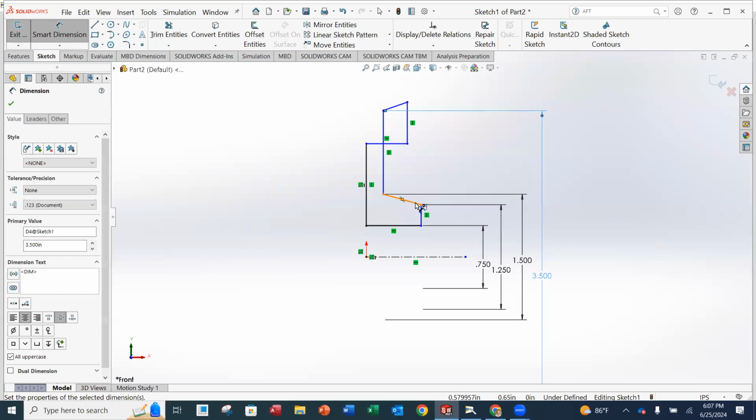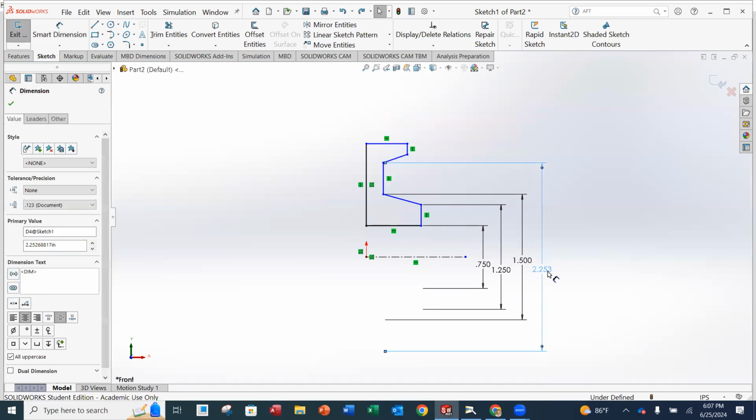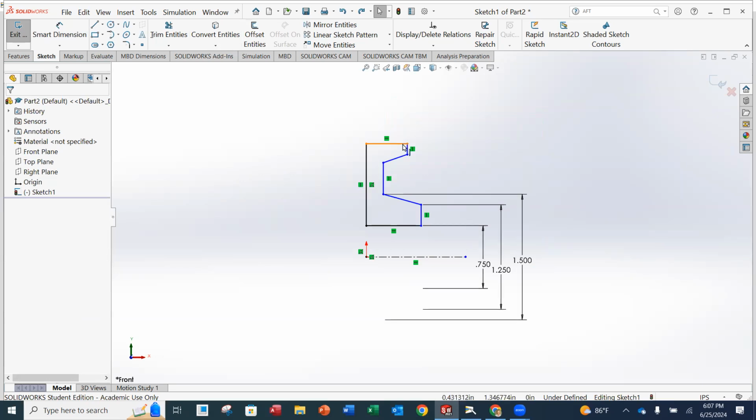If this happens to you at any point, what I like to do is say, oh crap, I'm going to undo that. So I'm going to hit my escape key and go up to my undo here. Okay. And instead of putting that dimension in, I'm going to take that dimension and delete it. I'm going to add the top dimension then, the taller one, because what happened was this went taller than what the